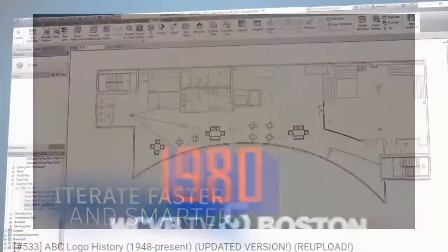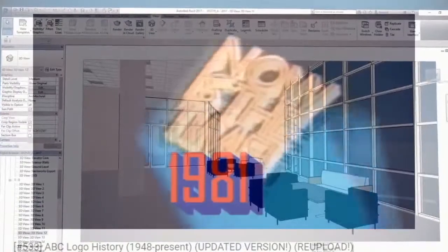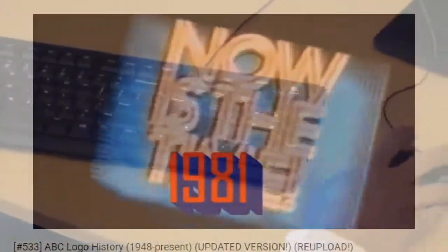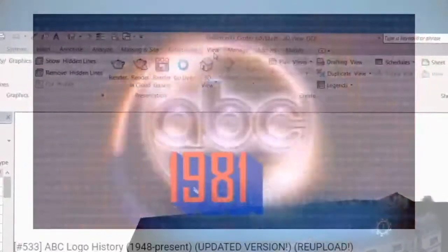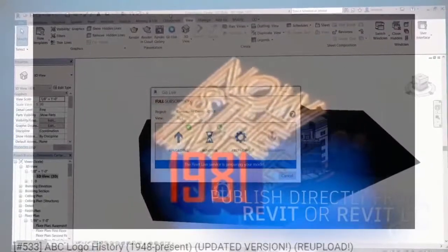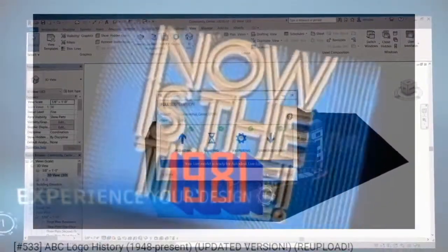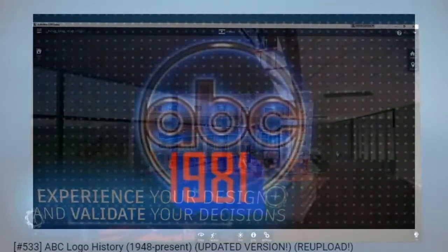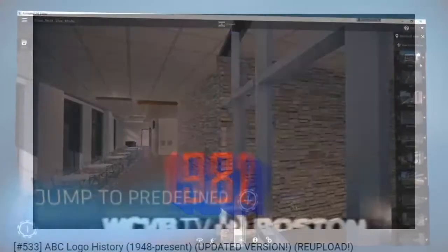You can constrain or lock the sketch lines to the interior walls, reference planes, and floor edge. You may do so in this exercise, but use constraints sparingly in larger projects to avoid slower model performance and updating calculation time. So we could lock these, or constrain them, for lack of a better term.